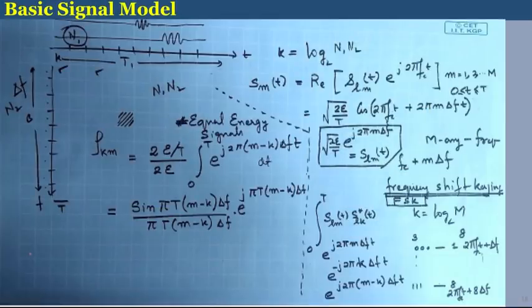So, what we were discussing in the previous lecture is basically that you have a set of frequencies, right? In those set of frequencies you can choose one of the frequencies to indicate signal carrying information, and let delta f be the separation between the frequencies. And along with that, if you have time domain, then you have basically n1 times n2 number of resource elements, and log base 2 of that is the number of bits that are required to identify the selection of a basic resource element by which you are communicating information.